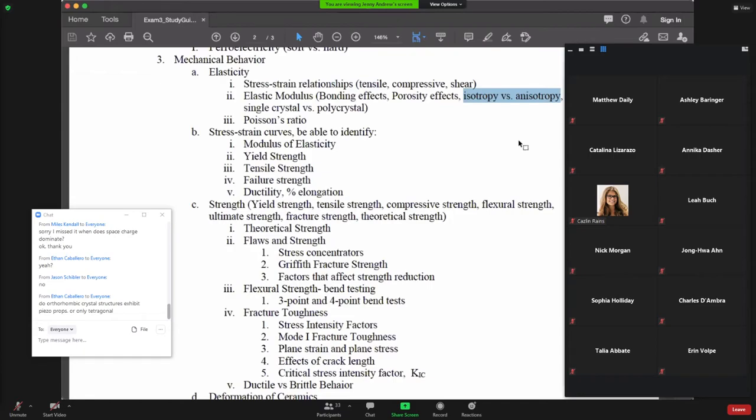Perfect. And now if you see any sort of preferred orientation, say elongation of grains in one direction, would you expect those properties to still be isotropic or anisotropic? If you have elongated grains, do you think the properties would be the same? No, anisotropic. Perfect. So then if you think one step further, if I take a sample and I anneal it, isotropic or anisotropic properties? Isotropic, perfect, because the grains will reform.